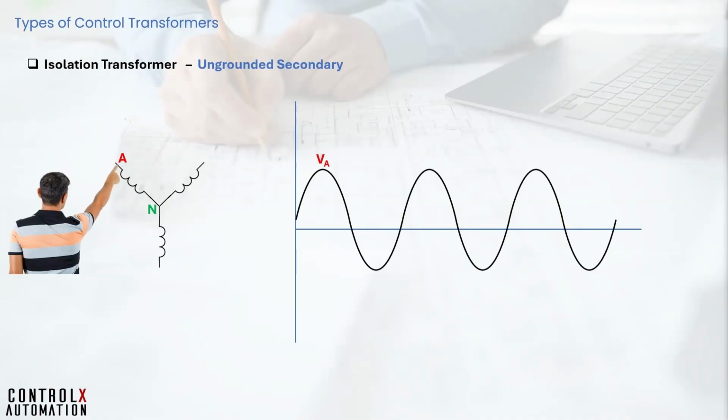This is because the net voltage difference between his body and the phase is almost 0, so no current flows through his body. However, there's still some capacitive charging current, which is typically very small, rarely enough to cause an electric shock. Now that the system has become a grounded system with one grounded phase, a second ground fault anywhere else causes the phase-to-phase short, which can result in a hazardous condition.